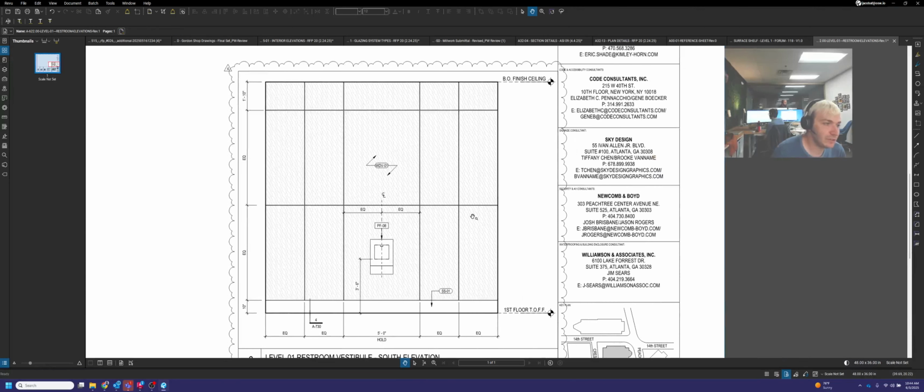One other thing to note is that with a typical wall of panels, we try to maintain specific panel dimensions. Our company has max panel sizes that we like to work with. We did talk about this briefly in the last video: we try to go no more than 48 inches wide typically and no more than 96 inches tall.